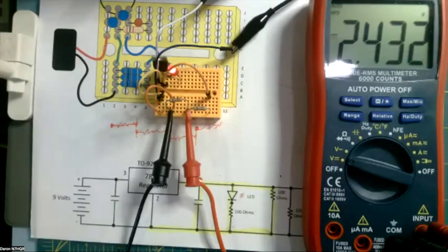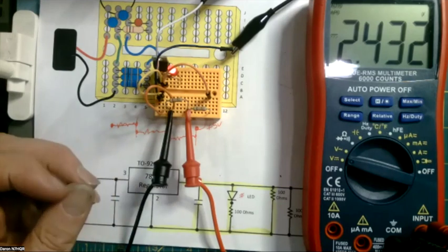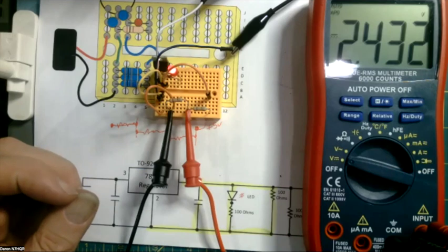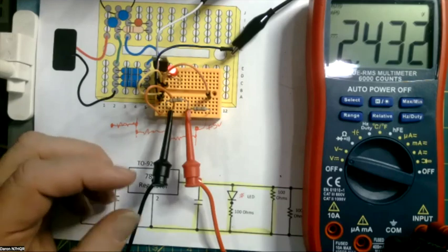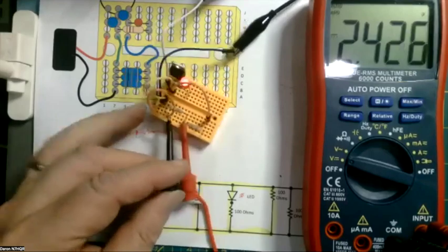John and Scott, I hate to interrupt what you're doing, but I want you guys to see this because it's important. Darren is measuring the voltage divider and finding that it reads 2.4 volts. We figured in our head it ought to be about 2.5, so that's plenty close. Now, Darren, get your Simpson and measure that voltage.